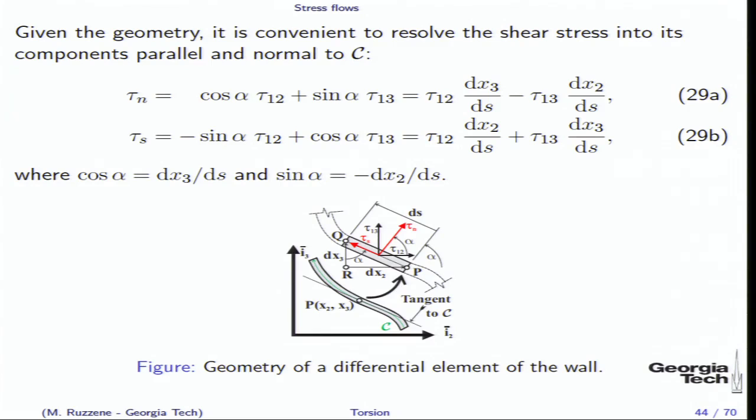For example, if we have a rectangular thick beam and we are applying a shear force at some point, the variation in the axial stress would be something like this, right? A linear variation. We don't have any torsion in this beam, so the variation along the thickness, which was linear, is not there, because that was for the loading condition when we were applying a torque at the cross section.